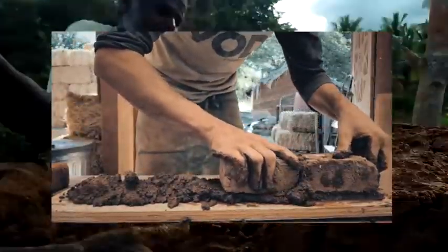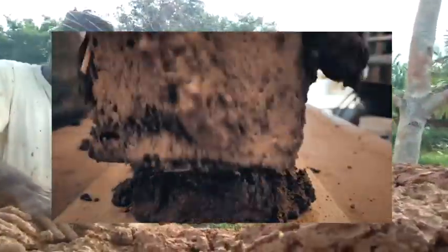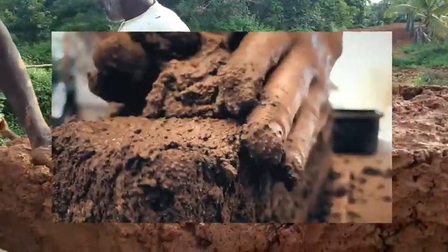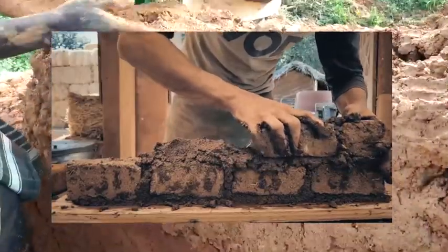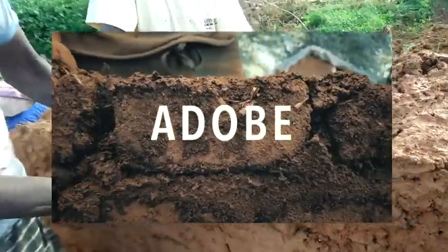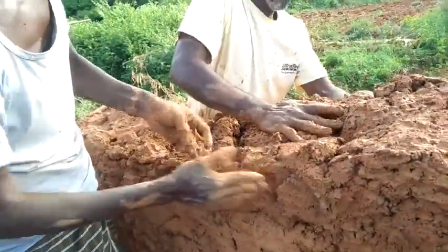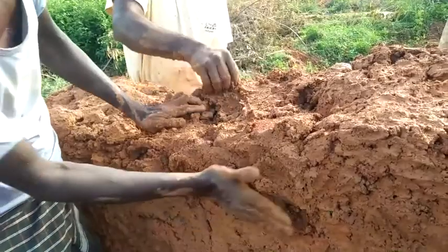On the other hand, rammed earth construction is a technique similar to adobe bricks, yet without having to wait for the mud blocks to dry in the sun. In this method, the mud mixture is pressed into a shape using wooden planks which are removed after some time. This compresses the air out of the mud and leaves it to harden in its desired form. This method is used in parts of the world where it rains more often, therefore hindering the adobe brick process.